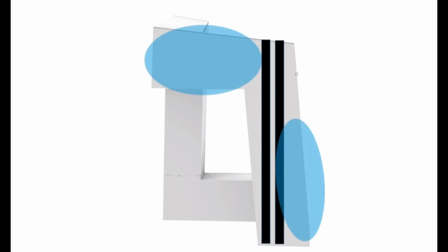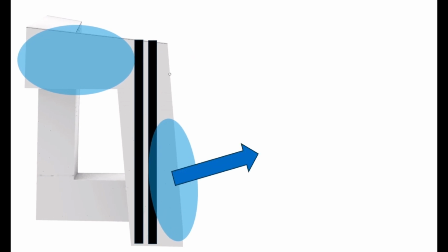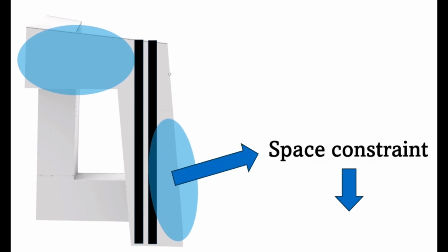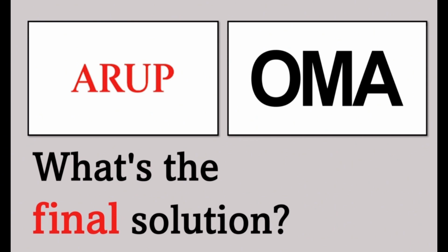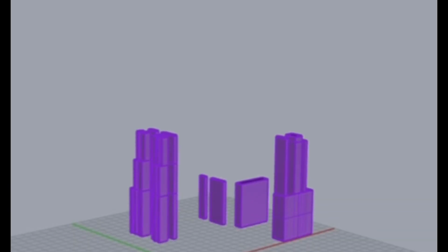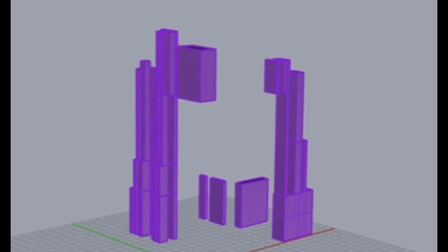However, if one vertical core is used here, like other buildings, the tilted structure limits the space where the core can be located. The importance of the core grows further in tilted buildings, which can lead to structural instability. To address this issue, instead of placing one vertical core, we chose to place multiple vertical cores at various heights according to the degree to which the building is tilted.